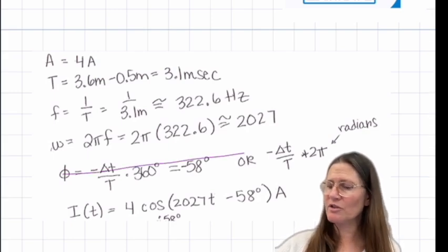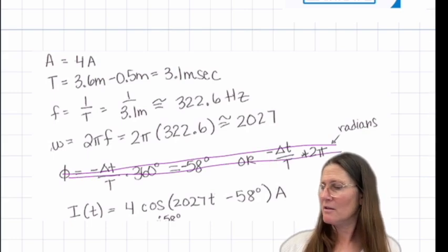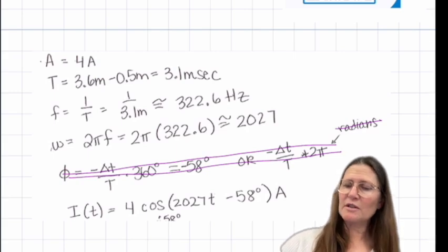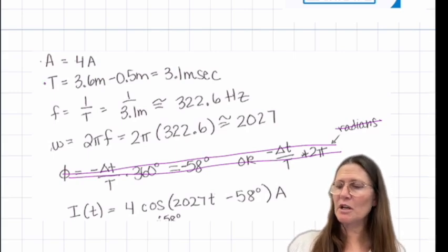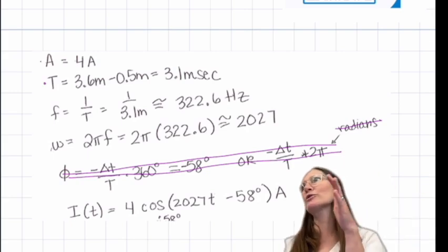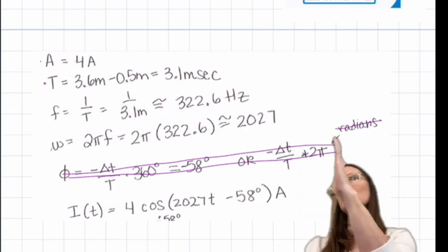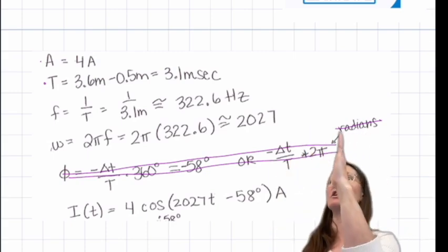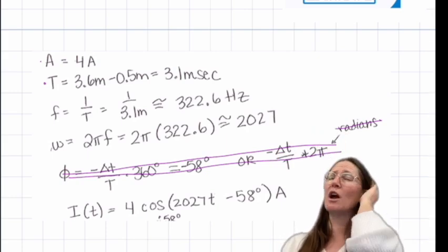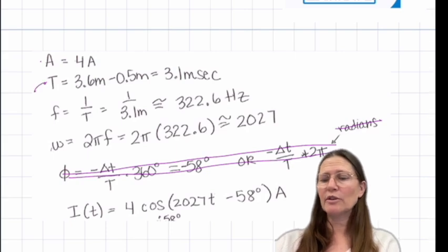Once you get the amplitude and the period, most of the time you're going to measure a period off of an oscilloscope, so you can put a marker and then you just drag it to where you're seeing the repetition happening. That's where you're going to get a measurement of your actual period. So this can be measured on an oscilloscope.